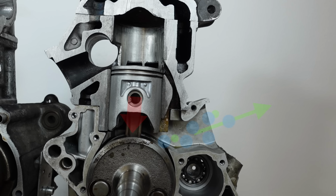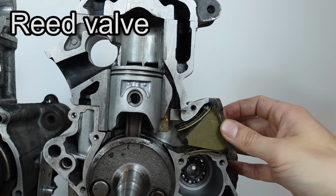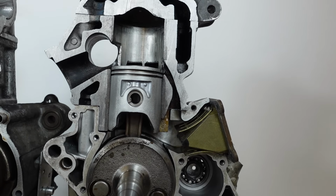To do that, many engines use this, and this is a reed valve, which is placed into the intake like so. A reed valve is essentially a one-way valve. It allows gases to enter, but it prevents them from exiting. When the piston moves up and creates a vacuum inside the crankcase, it also creates a low-pressure zone inside the crankcase, while a high-pressure zone remains outside in the atmosphere. This pressure difference forces the reed valve blades or petals open. Vacuum inside the crankcase means that there's very little pressure acting behind the petals, but there's atmospheric pressure acting on the other side of the petals, forcing them open.